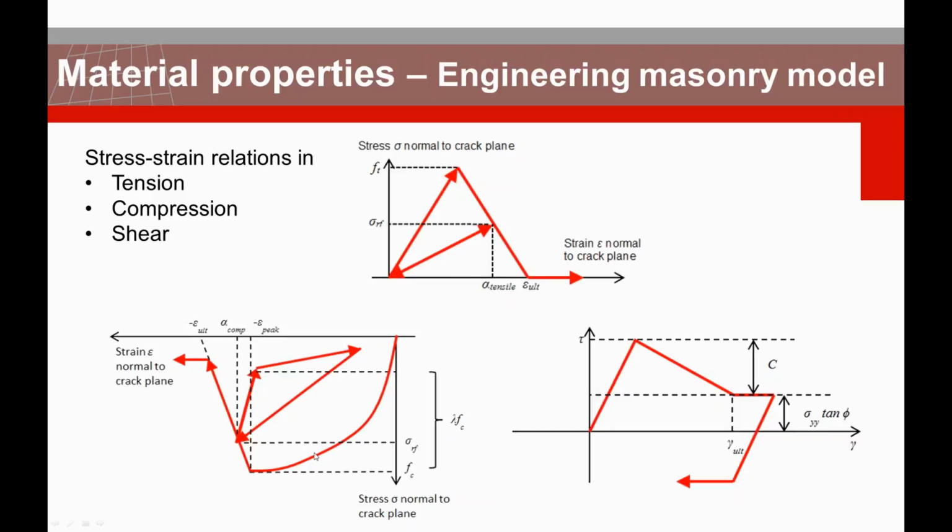This is when you have a compressive behavior. When you're dealing with the compressive behavior, you can specify your unloading, reloading as either linear or nonlinear, or basically plasticity behavior. Between 0 and 1, you can play with it, and here, for instance, we can define something between 0.2, 0.3, 0.4 to come up with some sort of not very sharp and brittle drop, and not secant unloading. So something in between to capture the loading, unloading behavior of the model. However, in the tension, our unloading and reloading is literally secant.